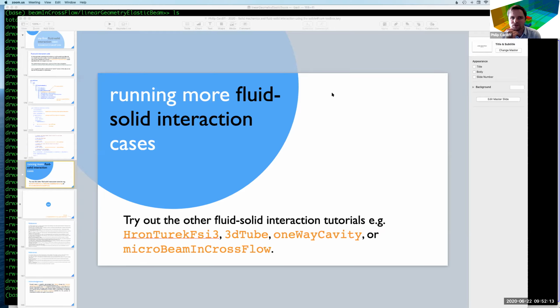I suggest you move your 0 directory, just rename it to _0, and then create an empty 0 directory and try it. There might be something in the 0 directory messing with it. Or if not, take your 1 result, maybe delete all the time steps except for 1, make a new 1 directory and copy in just one field, like the D field. Maybe not the D field, actually, say the sigma field. Open it then, see if that works, and keep copying in one field after another. My guess is if there's something in a D boundary condition, ParaView is confused by the size of what it is. OpenFOAM 19 must be printing out a different size or in a different format or something.